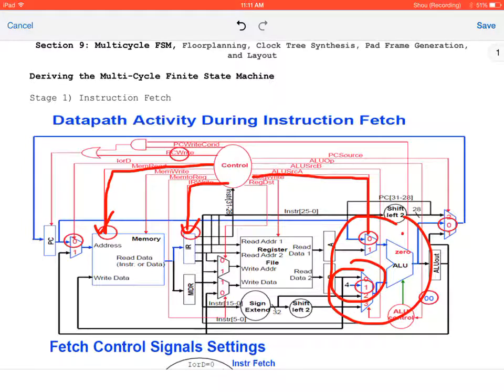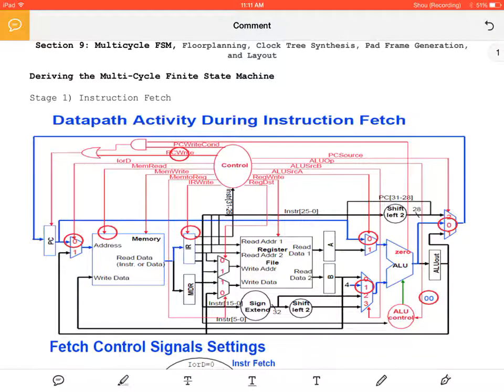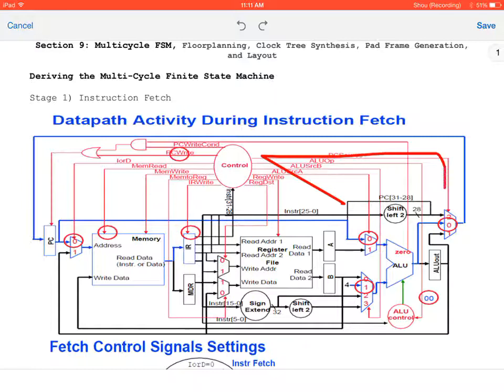It's going to use this finite state machine; the trade-off is a higher control area, but it's going to reduce the amount of memory and ALU that's being used, which is also why we set this to 0. We're using PC source set to 0 because we're going to immediately add the value in the ALU and then send it off and just get this next value.